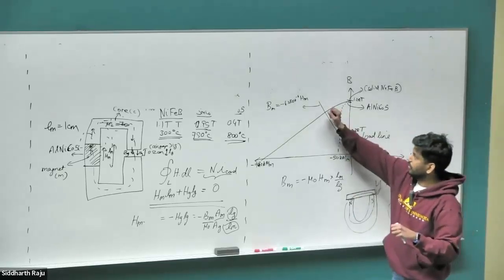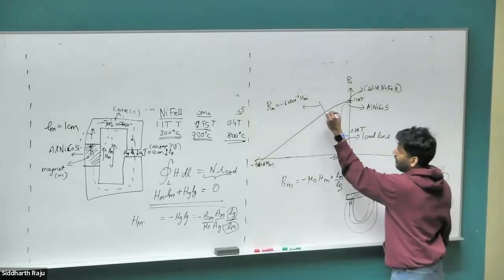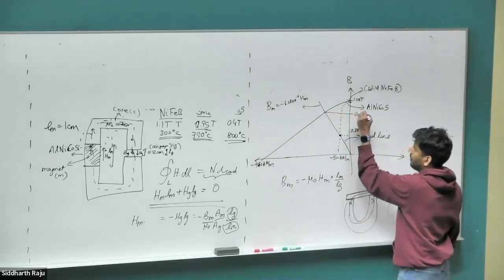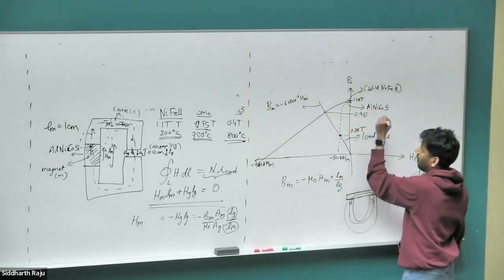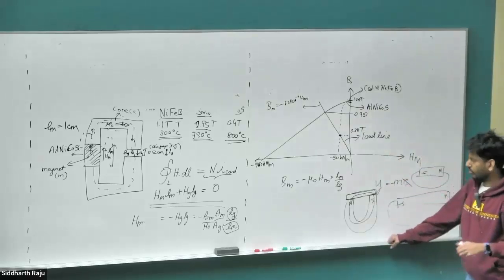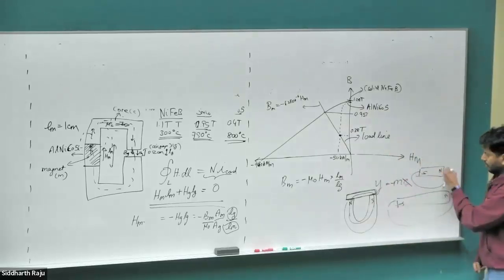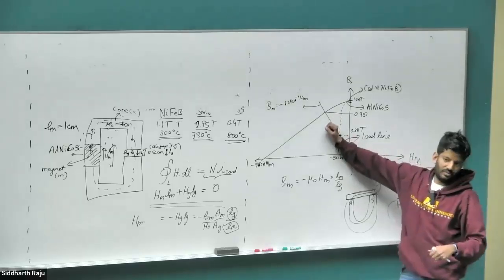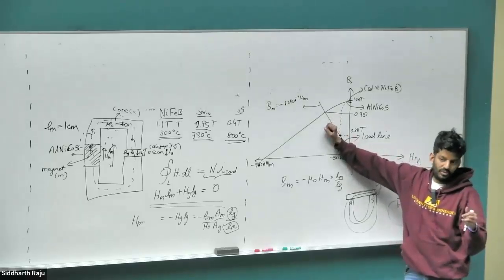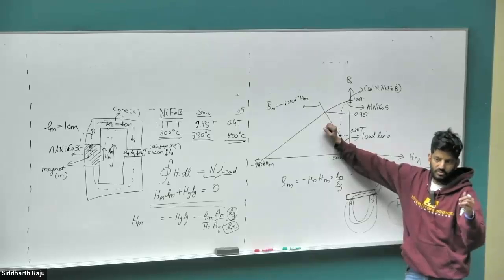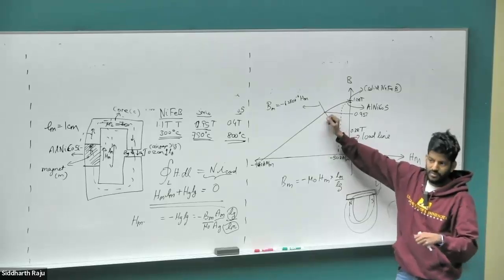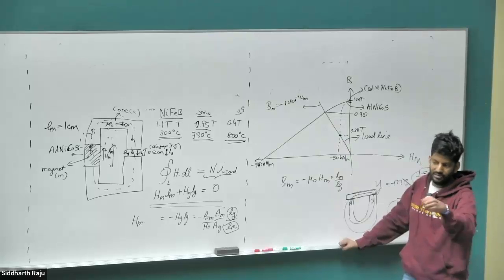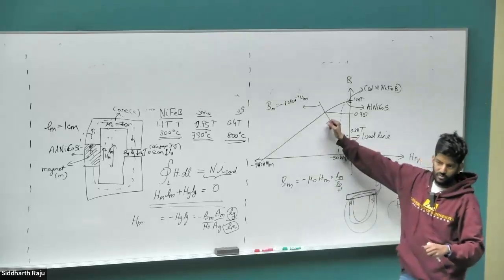But that's not the case with neodymium, because even in an open neodymium, the magnetic field settles down to like 0.95 Tesla or something like that. So with neodymium magnets, you get these bar shapes because even with the large air gap, external fields are not strong enough to demagnetize it unless you intentionally put it in a motor and pass current in the opposite direction, which can be large enough to demagnetize. But Earth's magnetic field or a current carrying conductor nearby is no way going to affect it in any way.